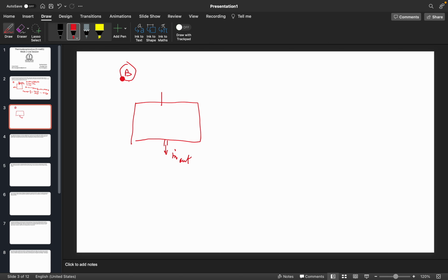And we already know there is a rate at which it comes in, m in. Now remember this m out is given in kg per second, so you can do both ways. You just have to make the unit the same. Either you convert this m out to meter cube per second, or you convert this m in to kg per second.